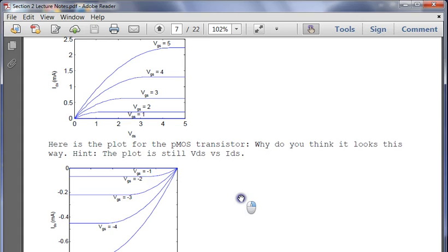So if you actually plot them all out, you'll get something like this, for the NMOS and for the PMOS. In order to get this exact value, you have to multiply the width of the PMOS transistor by 2, or you'll get something that looks more like this. You get something like, and you simulate, and we're going to be learning about SPICE later in the semester.